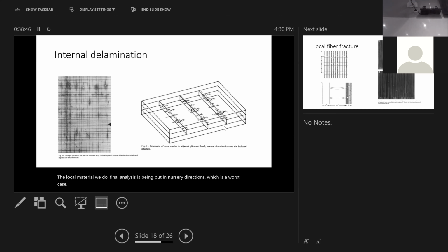for most material. Most material can resist pretty high compression. If you compress the material equally from all sides, you can argue some materials never break. They are infinitely strong. If you pull the material, it usually becomes weaker. If you pull the material from three sides, that's the worst case. Even ductile material, if you pull from three sides, can become brittle. Okay. So at those cross points, due to the adverse stress state, local delamination occurs, which is basically local separation.